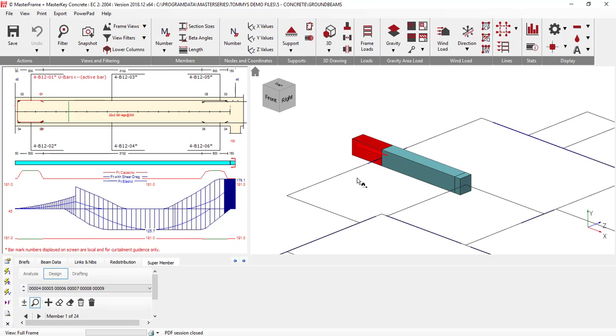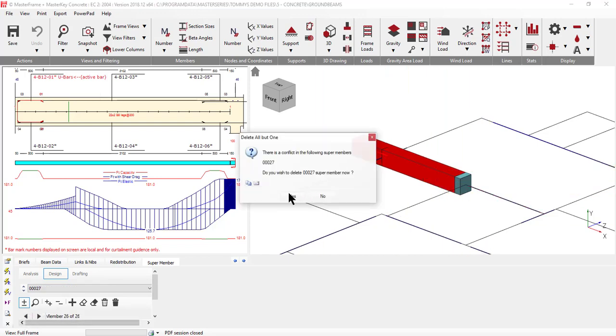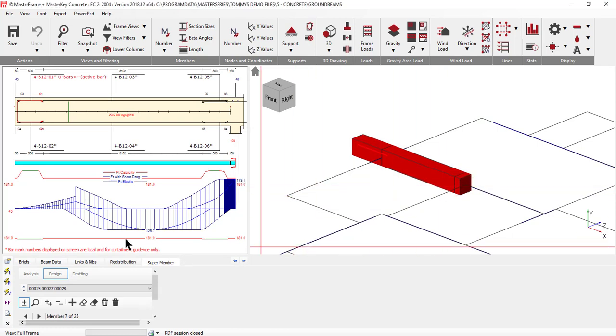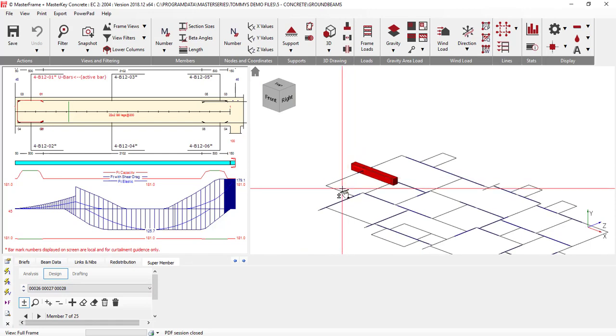Makes your reinforcement design a lot simpler than having this little small cantilever with its end steel and its support steel. Just run it straight through and it'll look after itself. What I could actually do is take this run and add that to that, so that it's all in the one run.